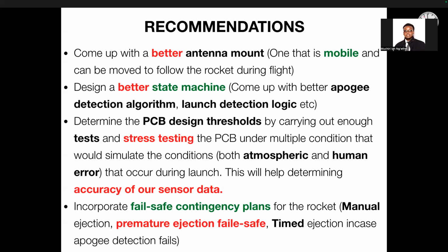We also need to determine our PCB design thresholds by carrying out enough tests and stress tests on our PCBs under multiple conditions to simulate the actual environmental and human error factors that happen during launch. Most of our designs and testing are usually under ideal conditions, where your PCB is just placed inside a room where the temperature is ideal, there are no movements, and there are no vibrations. So when you do the testing, it will obviously show you the correct values. But based on the experience we had during launch, these conditions are barely what you expect.